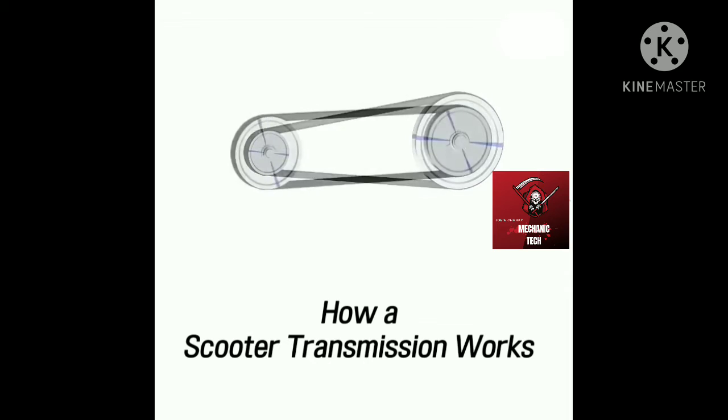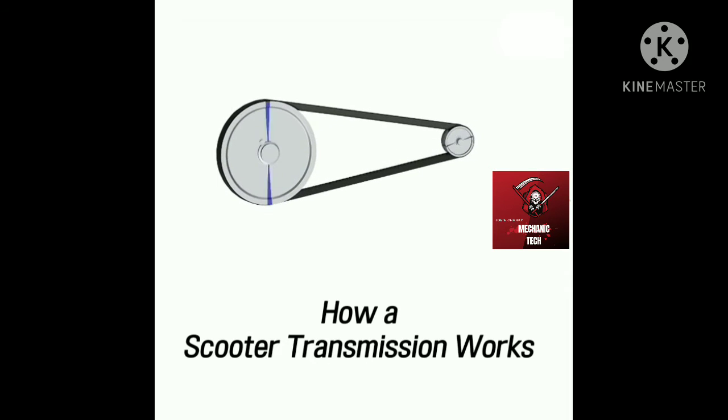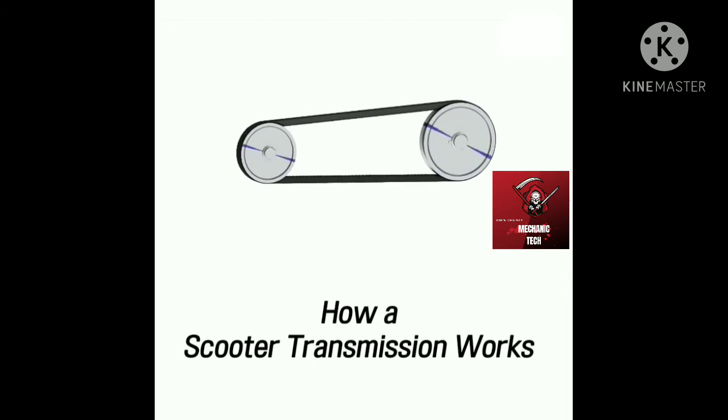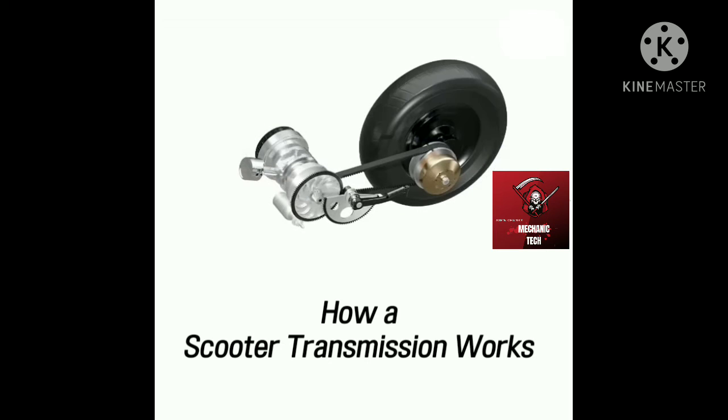It is not possible to simply change the diameters of solid pulleys as shown in this demonstration. So engineers developed certain mechanisms to obtain similar mechanical characteristics. A variator assembly is used for this purpose.